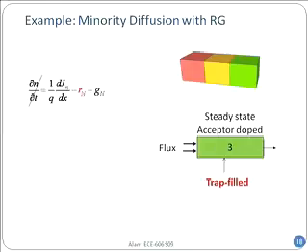I do not have any generation, and it is steady state, so I take out delta n, delta t. I get rid of generation. Why? No light. In that region, there is no light, so therefore I take out the generation. Now this time, I cannot take out the recombination because this has a lot of mid-gap trap levels. Copper, gold, these are mid-gap trap levels in silicon. Somehow they have gotten incorporated, so I cannot take it out. The electric field is 0, and correspondingly, the only thing that is remaining is the diffusion term.